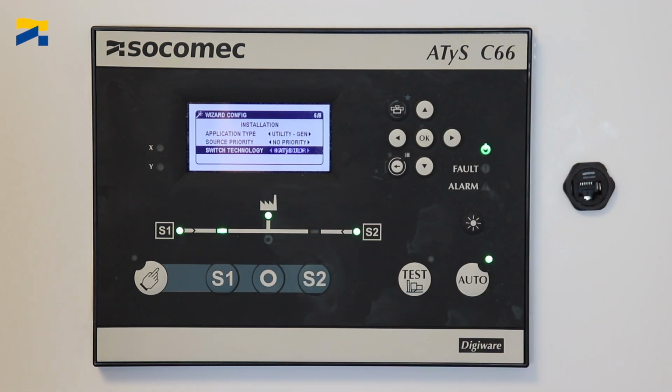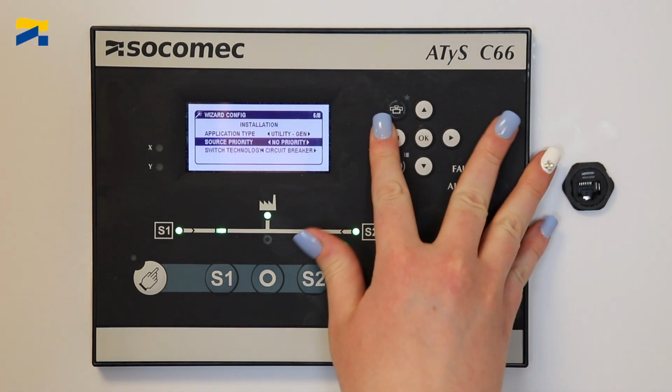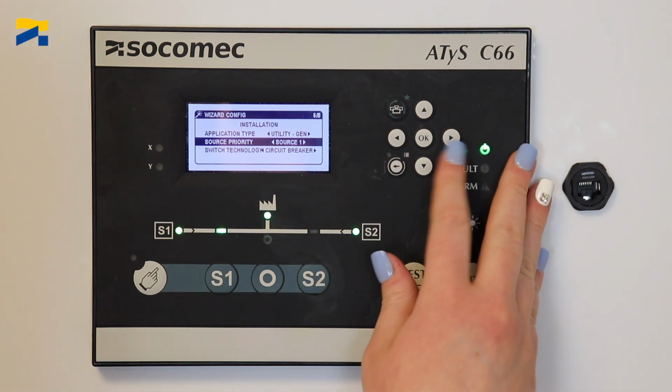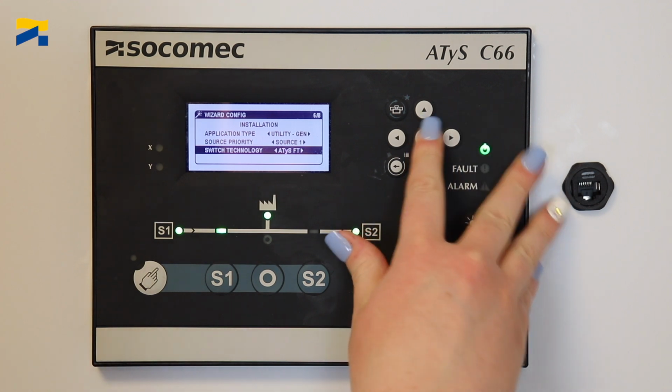The next option is contactor. This is to be selected when using two separated circuit contactors. And the last option is circuit breaker. This is to be selected when using two separated circuit breakers or air circuit breakers. So for our demo product, we will set the application type to utility genset, the source to priority 1, and the switching technology to the ATyS FT.